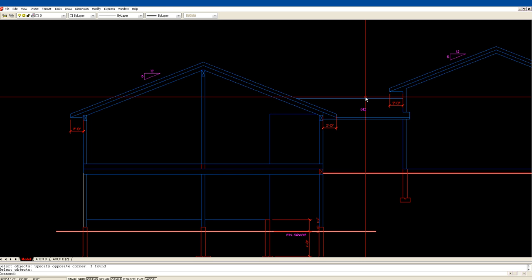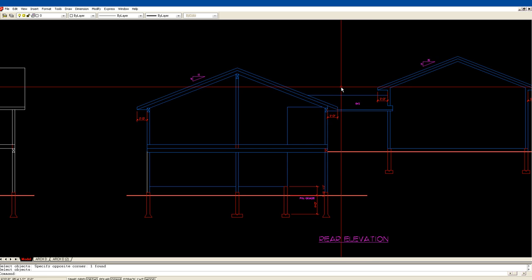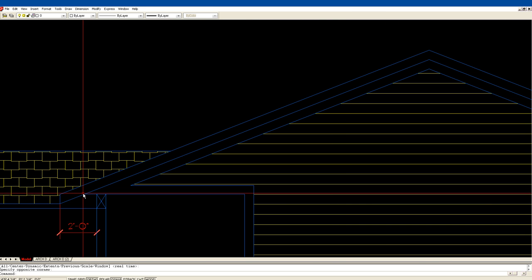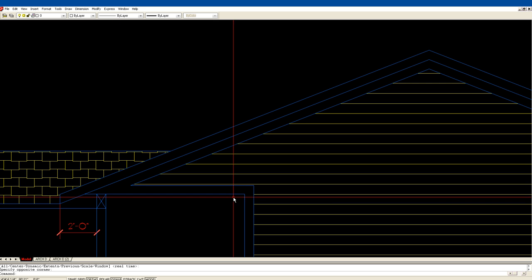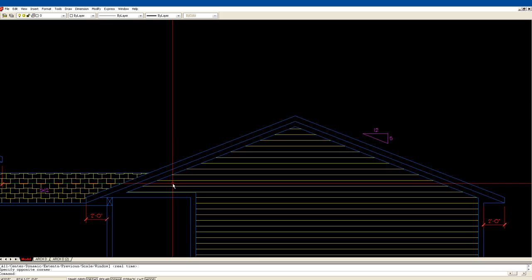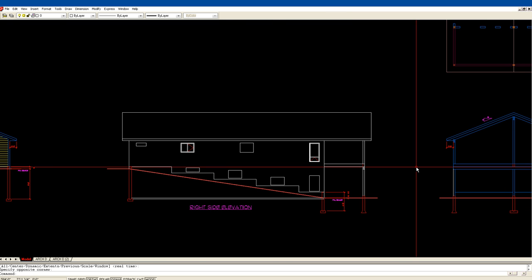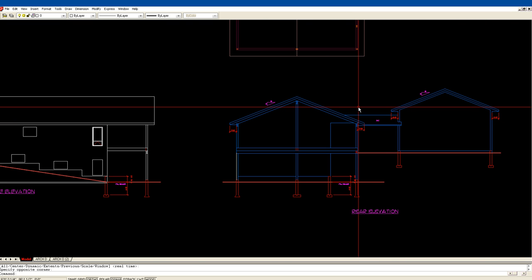When we're working with trusses, and when we all of a sudden shift over from the side of that to rafters, the beam's going to make a jog. So at the front of the house, okay, there's our beam elevation. You remember we put a truss all the way. The bottom of the truss is right in line with our ceiling. Yet when we go to the back of the house, we're going to have rafters, and so somewhere along the side of the house, the beam's going to have to drop down.